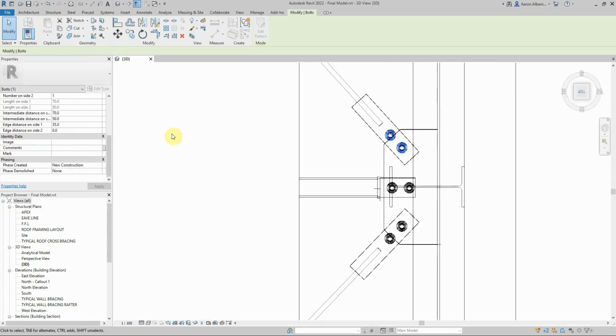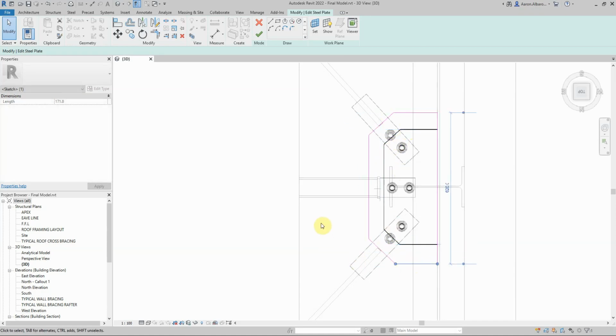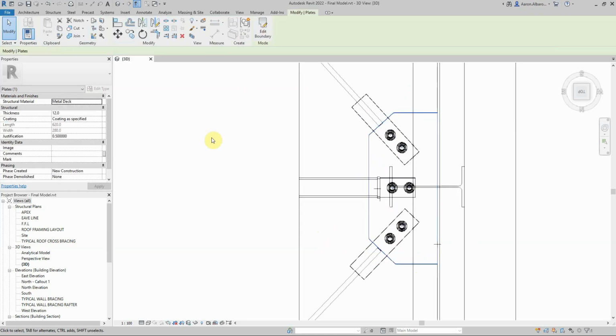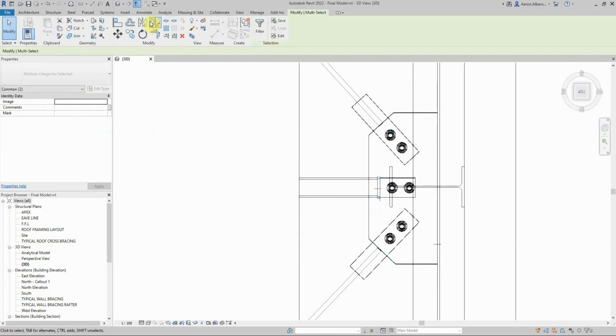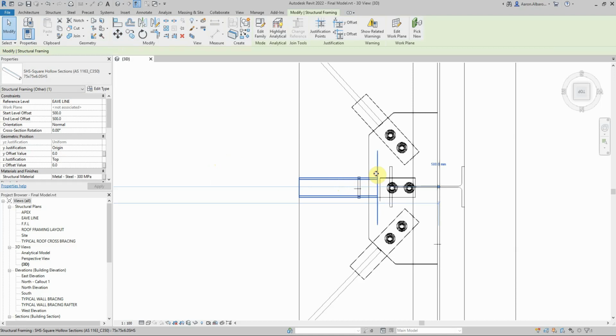Look at those when I click on them. They should be in direction number 1, or side number 1. So that showed us that our plate here needs to be larger to provide that correct edge distance. So I'll double click on it, and again we'll do the same as we did before, and you see now we stretch the plate to work out exactly what we want, and go OK. And it seems that I have to move this plate a little bit to the back, about here, and I have to move that, shorten.